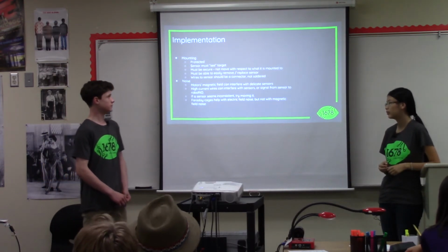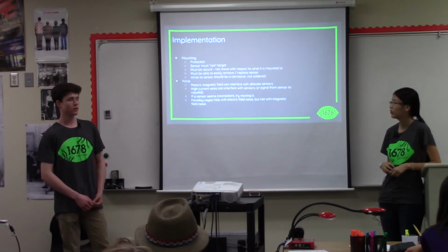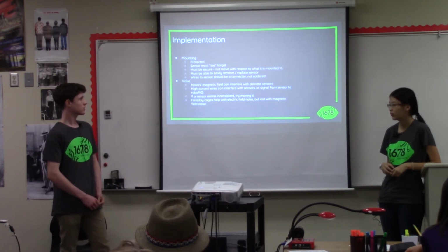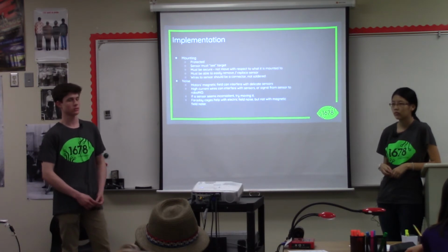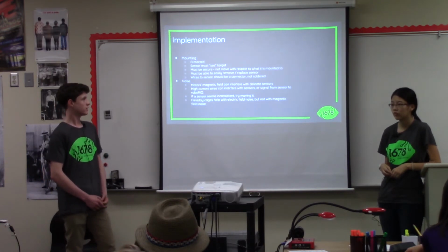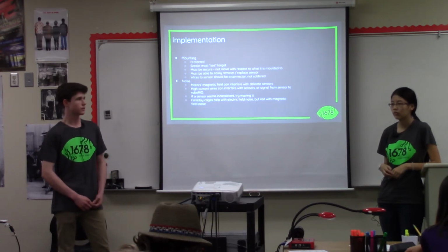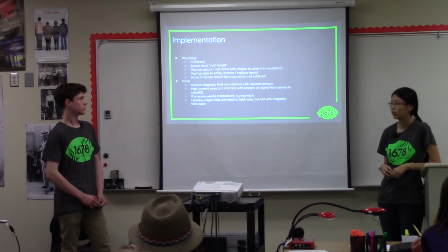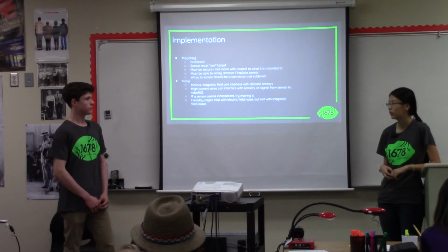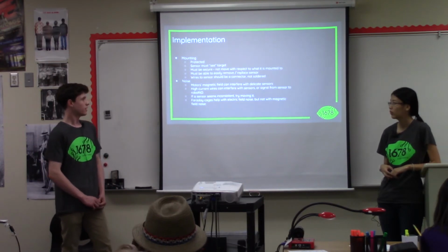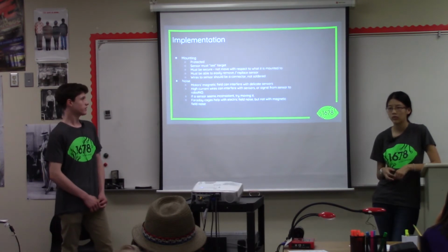Another aspect of implementation is noise. On a robot, there are many motors which give off magnetic fields, and they can interfere with the sensors, especially delicate ones. So you have to consider where you're positioning the sensor, and whether it's in a place where magnetic fields will interfere with it. One way to reduce this effect is with Faraday cages.